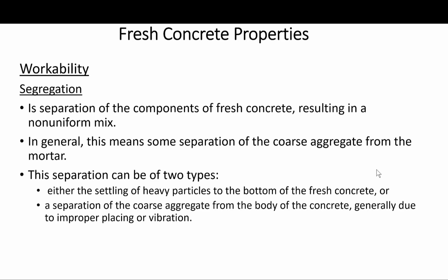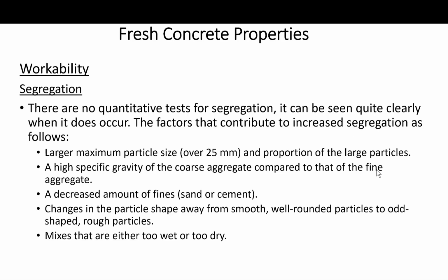This separation can be of two types: either the settling of the heavy particles to the bottom of the fresh concrete, or a separation of the coarse aggregate from the body of the concrete, generally due to improper placing or vibration. Although there are no quantitative tests for segregation, it can be seen quite clearly when it occurs.